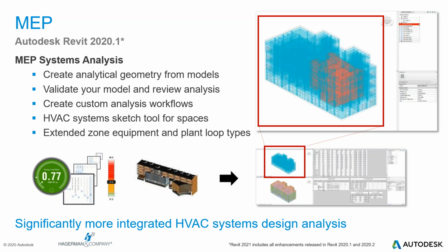And once systems and the zones they serve are defined, analytical models can be generated. Designers can then use Revit views and schedules to validate that their systems are properly defined and connected before the analysis begins by exploring their analytical systems in the systems browser.